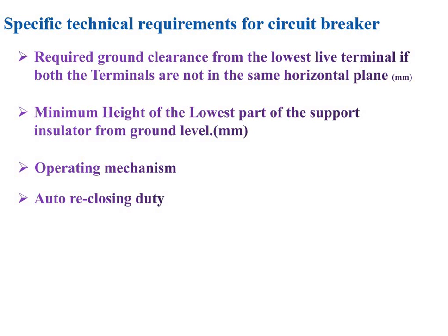So we can mention the total number of reclosing duties. If we want reclosing once, twice, thrice, etc. The auto reclosing duty generally preferred is the single auto reclosing duty. Means once the fault is there, the circuit breaker trips, and to check the type of fault, we can again close the circuit breaker contacts, and if the fault is there, then it will trip again.